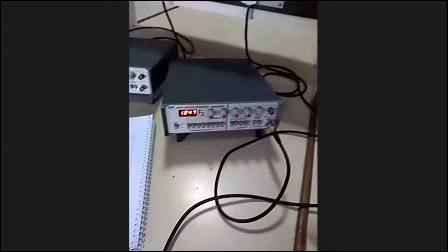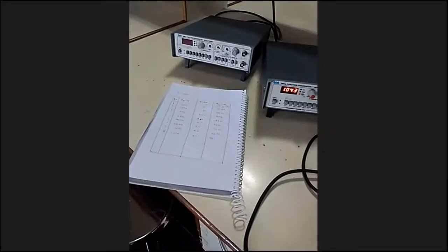So you will vary this and we'll see what the output voltage is. That's how all the frequency response characteristics need to be done. When you plot this on the graph, you get a graph similar to the first experiment. In the first experiment, we showed you how to draw on the semi-log sheet, right?